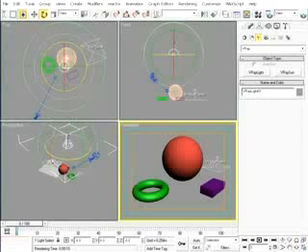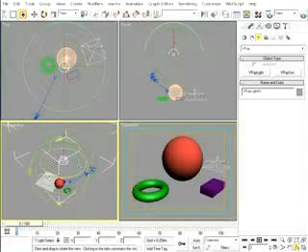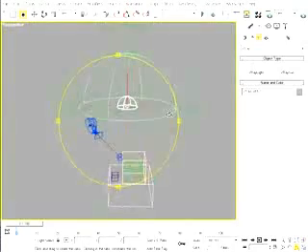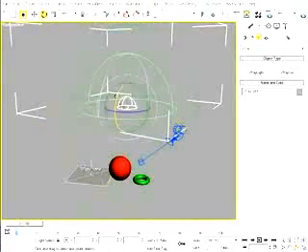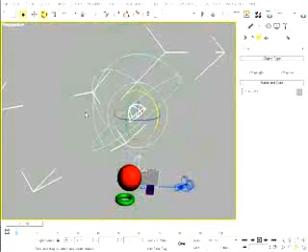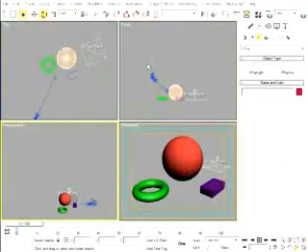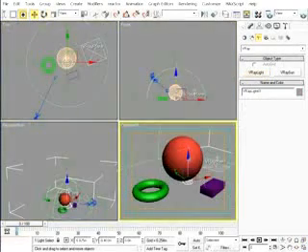So you should be able to visualize this dome as a virtual hemispheric object surrounding half of your scene and casting skylight from just that half of your scene. So the strongest light comes from the direction that the light is oriented. As I just mentioned a moment ago, the position of the light means nothing. If I delete this current light and drop in another light and move it just above the objects in my scene and render, this is what I get.